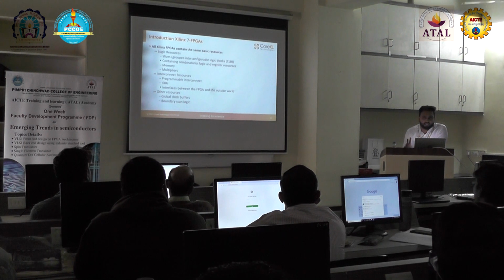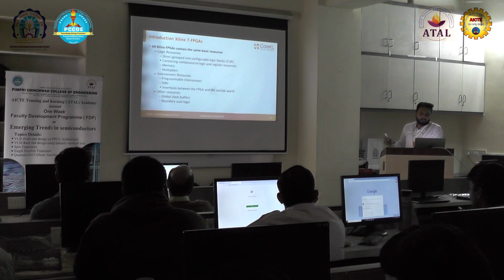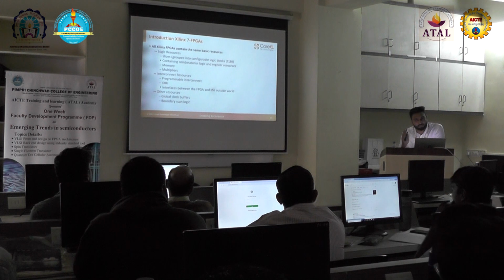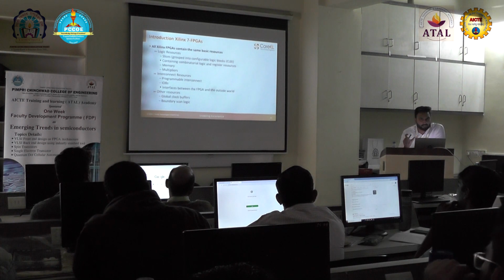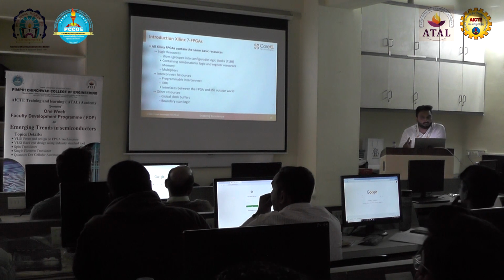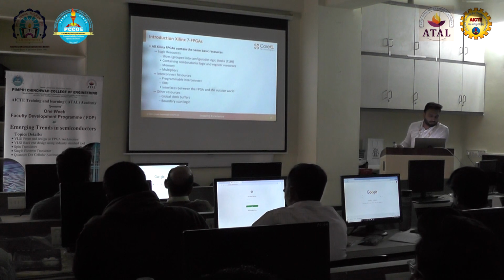The difference between DRAM and BRAM in the logic resources is that distributed RAM doesn't have any reserved SRAMs, but BRAM has the reserved SRAMs where the BRAM implementation can be done. Understand, this is the difference between DRAM and BRAM in the memory block of logic resources.